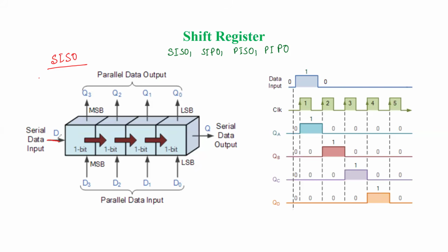For the construction of the shift register, we are considering the D flip-flop. Since we know that the D flip-flop is a transparent flip-flop, where whatever input you give will appear at the output, as well as being economical to use. In case of serial in, data will be given at the leftmost flip-flop. If you are performing the right shift, the leftmost flip-flop is given the input, and the rightmost flip-flop is going to give us the output. So from here we'll get the data output.